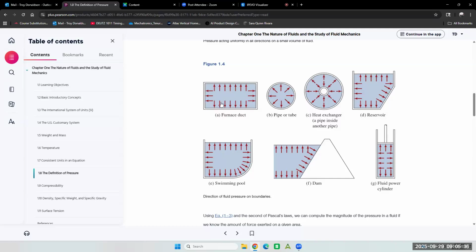Well, this cold air return is usually pretty big. It can be 2 feet by 1 foot, and it's that really thin sheet metal, and it runs under your home or in the walls of your home. In old homes, it's in the closet kind of thing. When you fire that fan off and the pressure gets created, the sheet metal on the edges can pop in and out, and you can hear it go bonk.